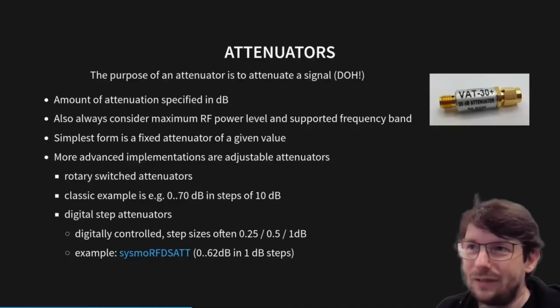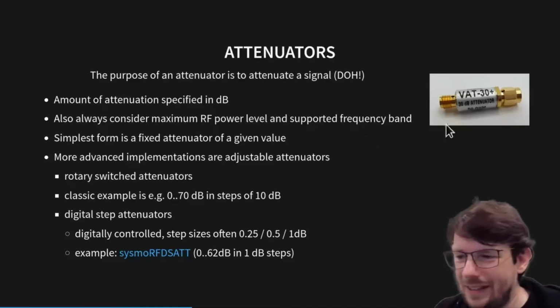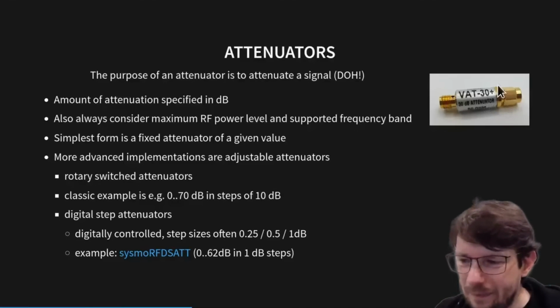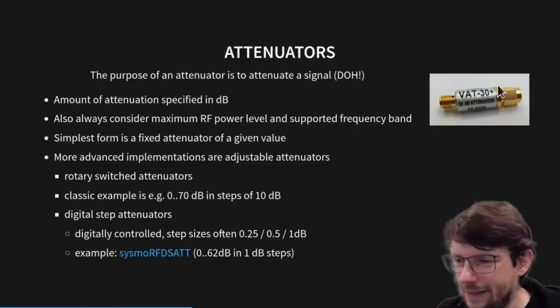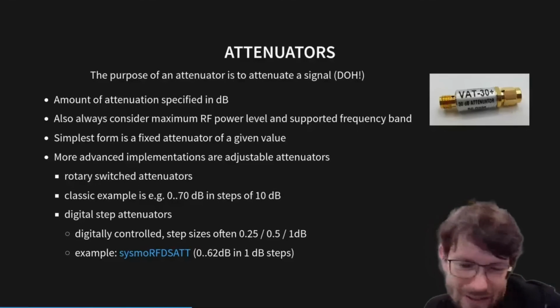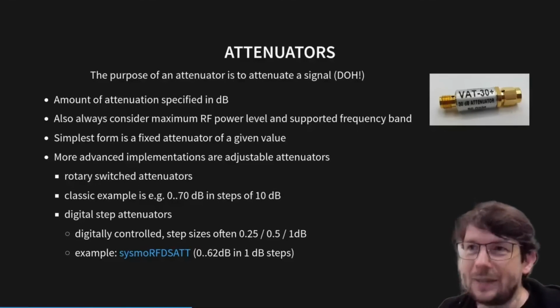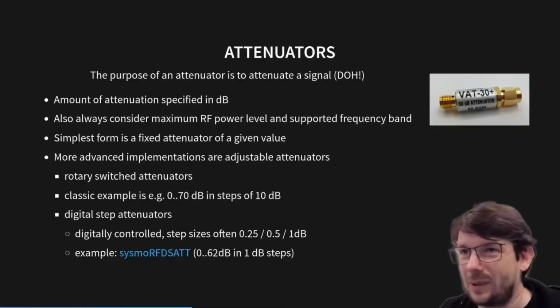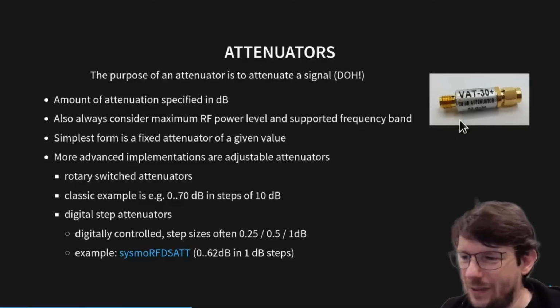On the other hand, if you use this device attached to a user equipment, you should generally be fine. Even if the user equipment could, in theory, transmit 2 watts, let's say a GSM phone, a GSM phone will only transmit 1/8 of the time. So on average, your transmit power will be only 1/8 of 2 watts. So it shouldn't be problematic, even if it's only rated for half a watt.